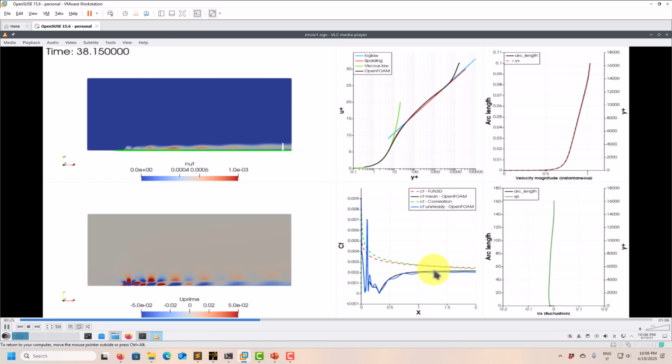Now get those statistics. So advice, never forget to compute your statistic in your simulation. So see here that I have a statistic for friction coefficient. That quantity exists, I'm getting that value. And probably here already, maybe you can say at 60 seconds it's not changing anymore, but probably here, let's go to 30. Maybe you had the false impression that this was okay. But look at when you evolve and you move to another instant, see that it is changing. And it still is changing from 60 to 70.